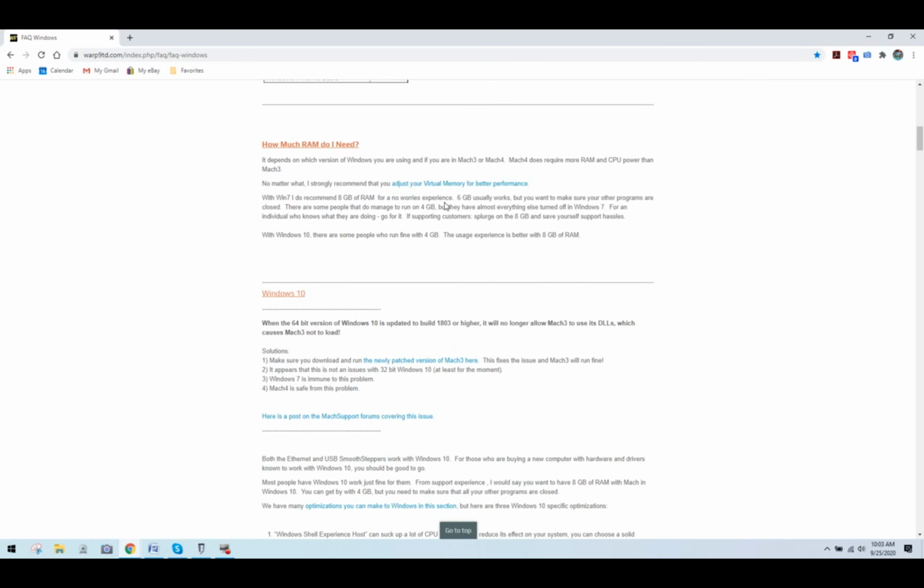And again, that's based on ESS, which is pretty amazing because the ESS really takes a lot of the workload off the CPU of the system. But CNC is labor intensive, and on top of that, when you take that labor intensiveness and then amplify it with the fact that we're running a newer operating system on old hardware, it makes it even more stressed. It just doesn't make sense. Be on the safe side. 8 gig is set. I recommend personally for any CAM system, and if you're doing CAM work at all, many of you guys understand it, 16 gigs is really optimal.